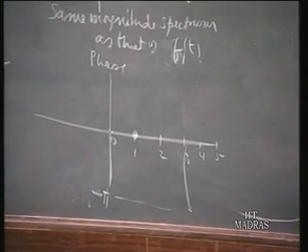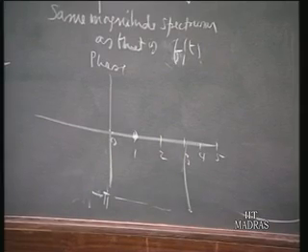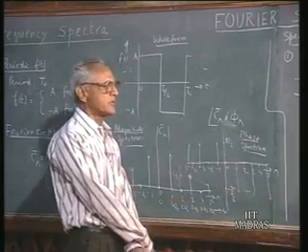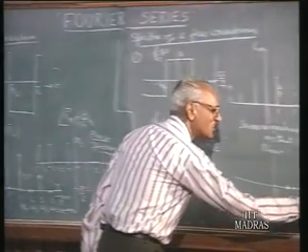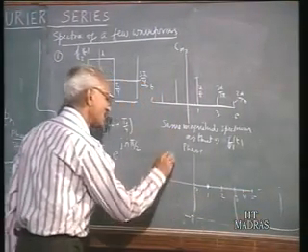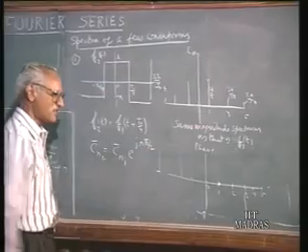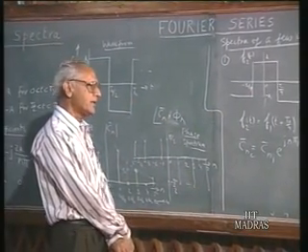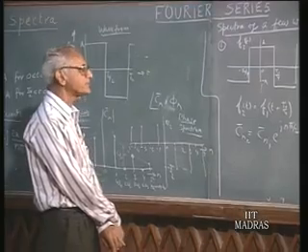And at 5, it's already minus pi upon 2, you add 5 pi upon 2, it becomes 2 pi, once again it is 0. So you have a whole series of angles 0 or pi alternately, and this is the phase spectrum.